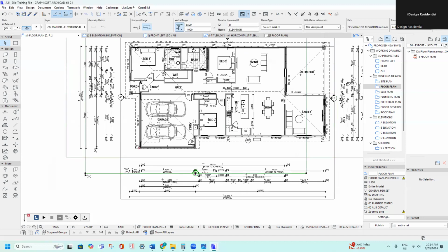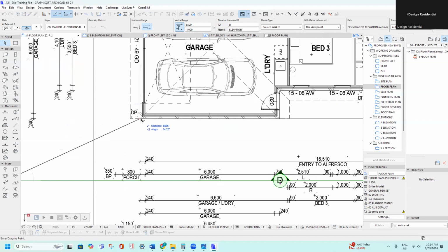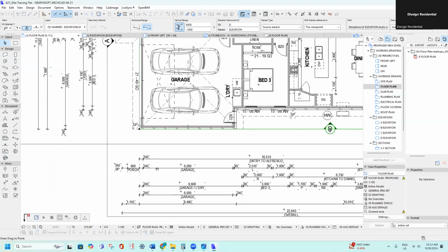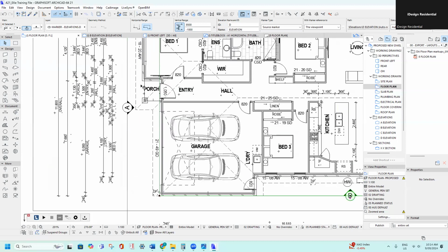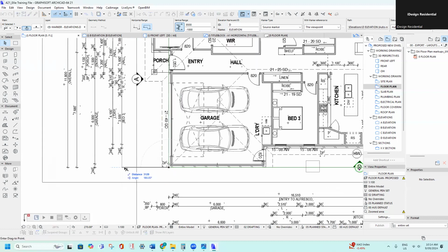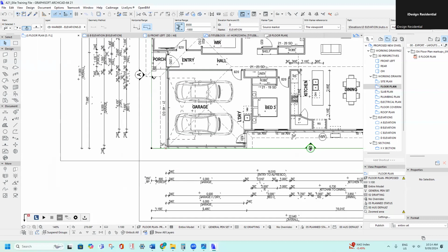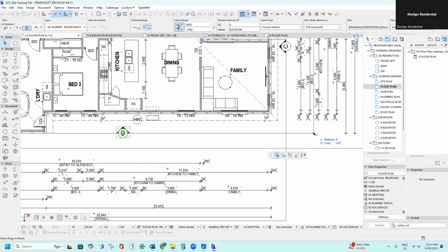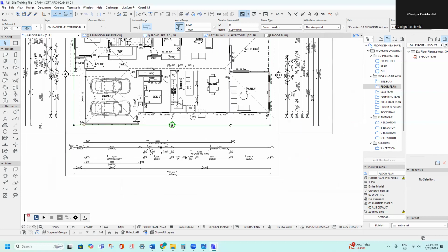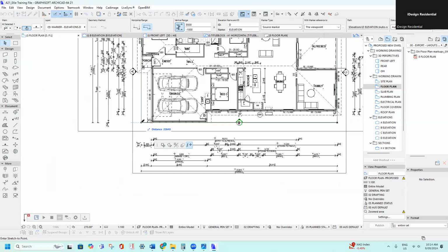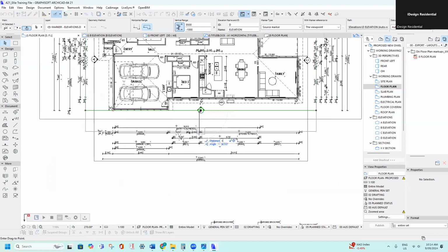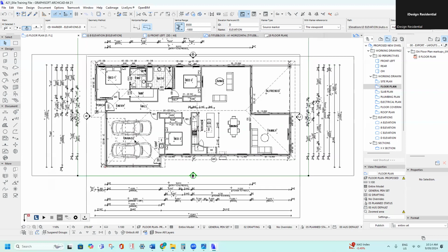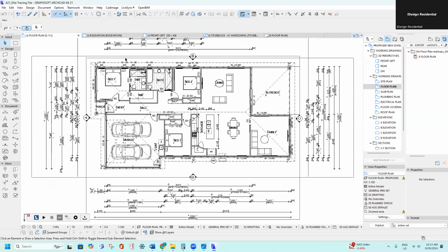And then I'll click on this one. Because the garage sits back from the front of the building, I'd actually drag it up to the front of the building for this particular one. Line it up at the back and then add in 4 meters. So 26,640. Control D, move it 2 meters that way, move it down a meter. And that's the elevation markers set up now.